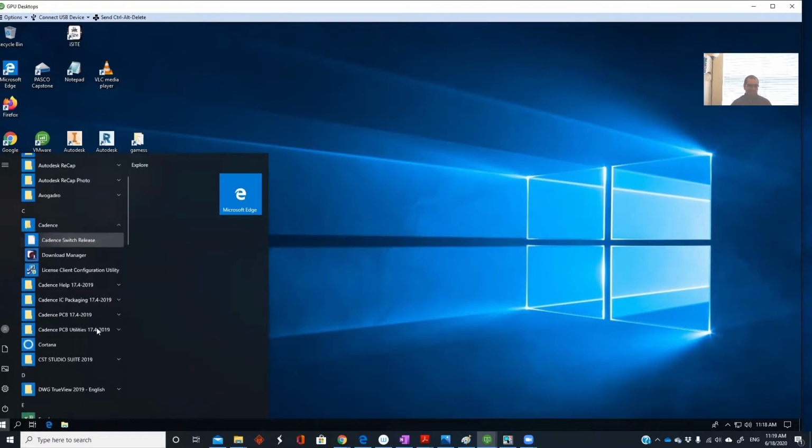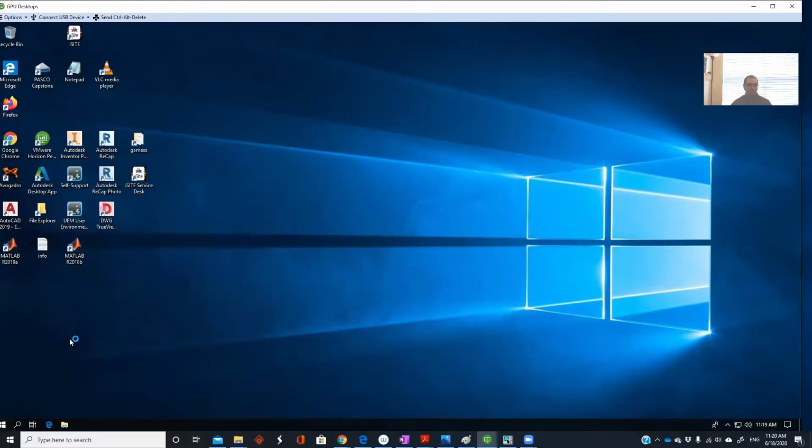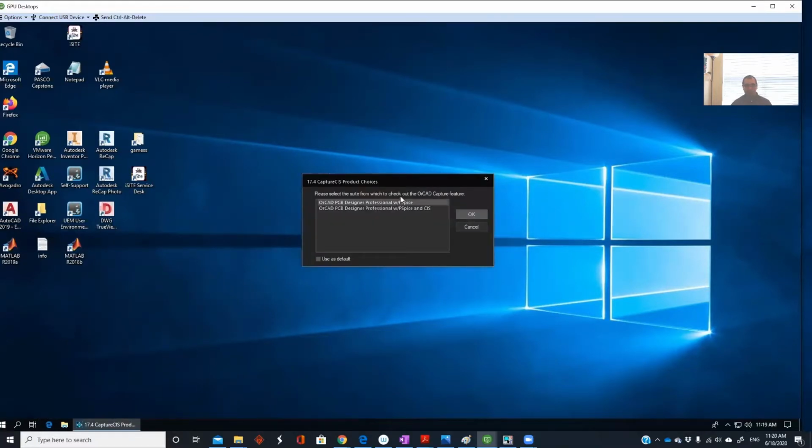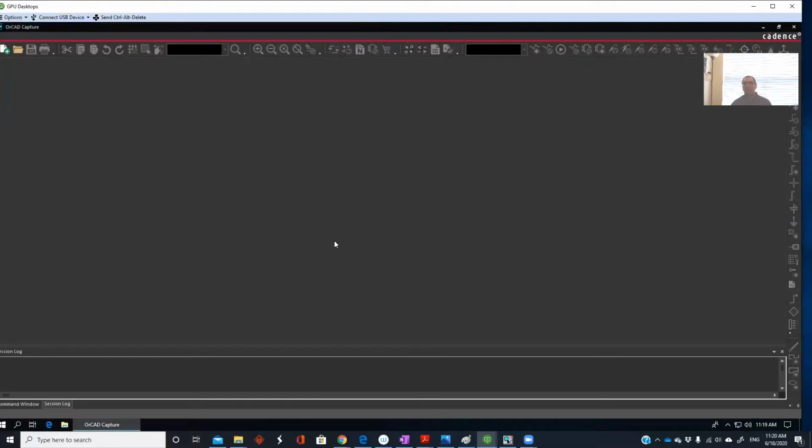From Cadence, I want you to go to Cadence PCB. This is like 2020 software, so it's very new, even new for your instructors. So let's see, what do we need to select? Here we need to select Capture CIS 17.4. You could choose either one, and I would just select the first one and click OK. As you see, this is very new, updated software.